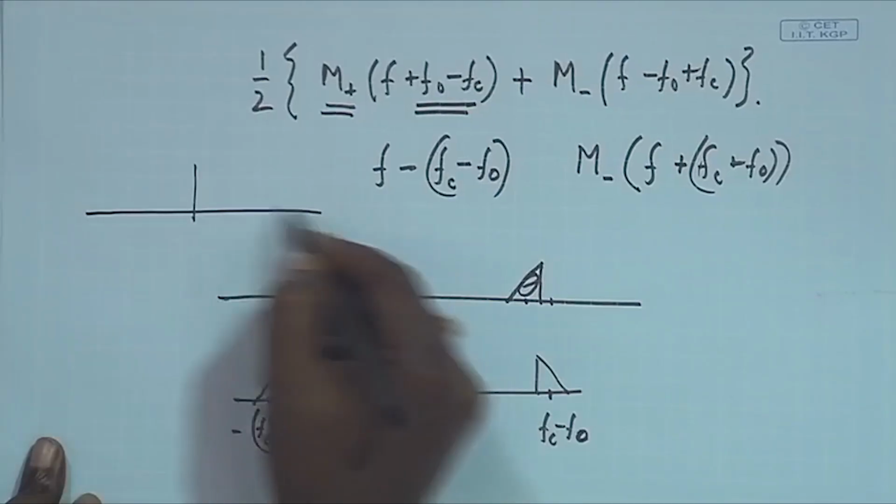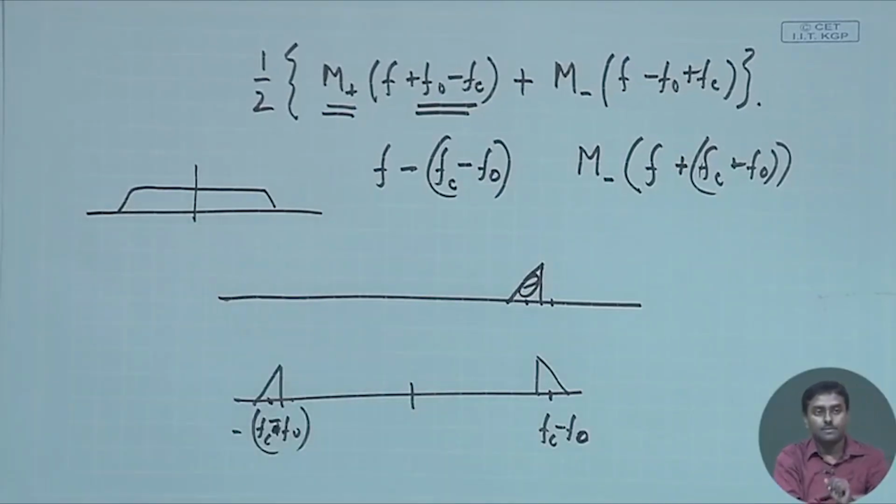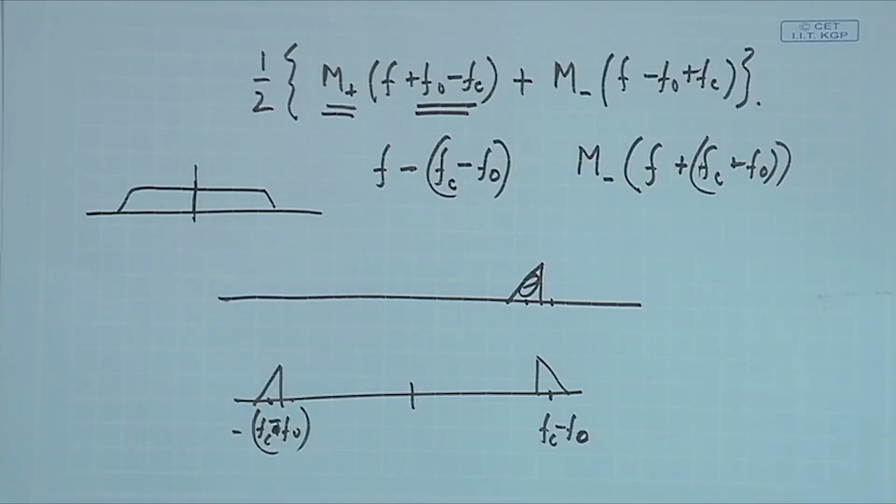If I modulate it with DSB-SC, I will be getting almost 9 megahertz, but I know that I will not be able to employ SSB over there, because the video band occupies the low frequencies, it looks like this. So, no way I can put a filter like this. Whatever I do, I will never be able to employ this filtering. So, there is a big difficulty in this, and I will never be able to work it out in video.